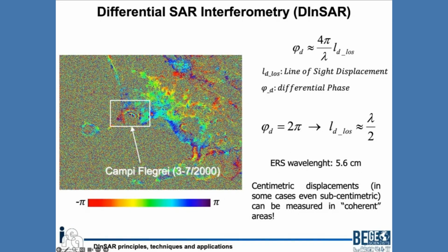So from blue to blue, we have 2.8 centimeters detected by the technique. That means something changed by 2.8 centimeters. So if we move from this blue to this blue, and then from this other fringe here, we can estimate essentially the displacement that in these 4 months corresponds to more or less 6 centimeters.